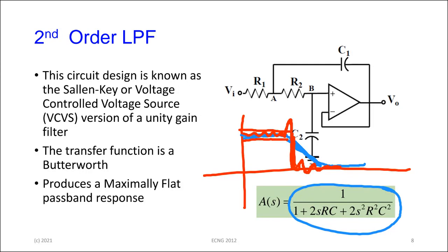So for instance, maybe in a hearing aid, where you're stopping certain frequencies outside of the audible range, but you want whoever is the user of the hearing aid to hear all the passband frequencies relatively constant. You may use the Butterworth type of design. But if the signals that you want are very close to the ones that you don't want, then you're going to sacrifice a little bit of ripple by making the transition from passing to stopping very quick. Those are design considerations.